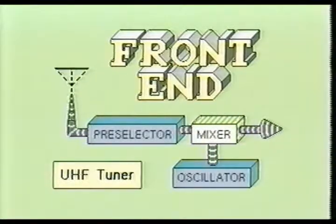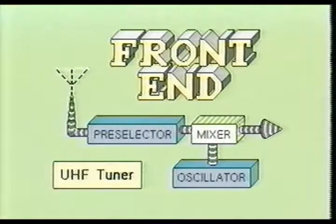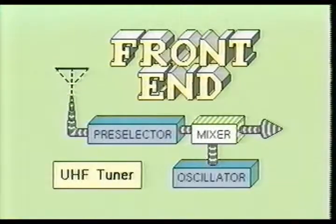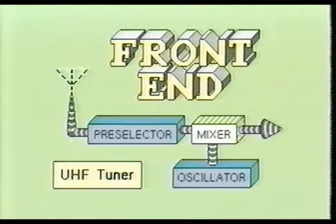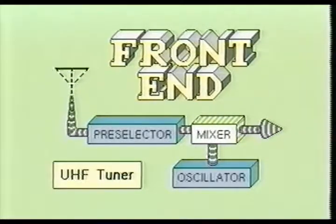The primary function of the mixer stage is to combine the RF signal from the preselector section with the RF signal being produced by the UHF oscillator stage. When the mixer combines these two signals, it will output a difference frequency, which will become the intermediate frequency value used by the tuner stage.